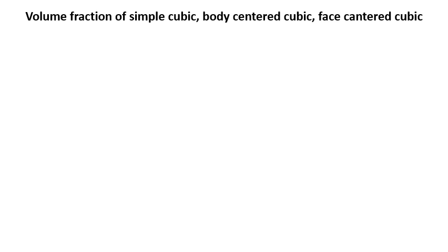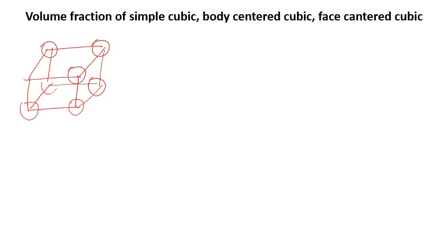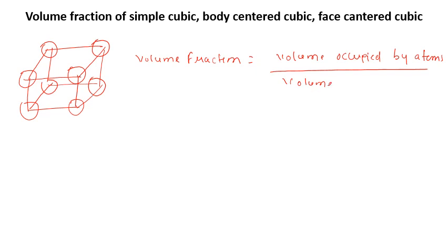So now come to our topic, the volume fraction of the simple cubic, body-centered cubic, and face-centered cubic. Let us start with simple cubic one. Let me draw a unit cell here. So for the calculation of the volume fraction, first we will try to find our recipe or our formula for the volume fraction. Volume fraction is equal to volume occupied by atoms divided by the volume of unit cell.